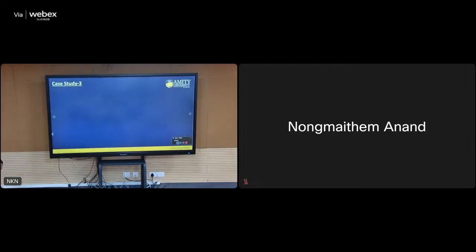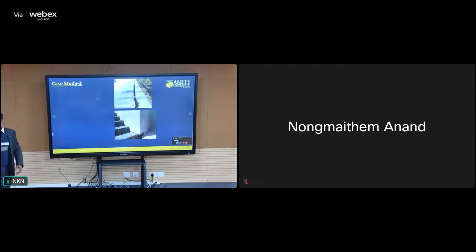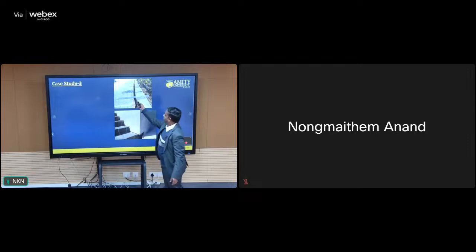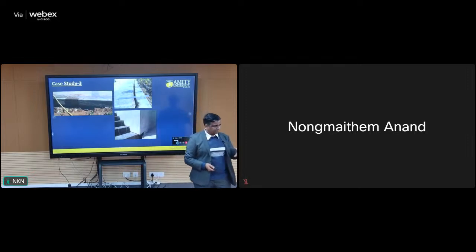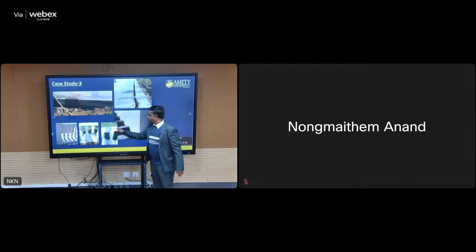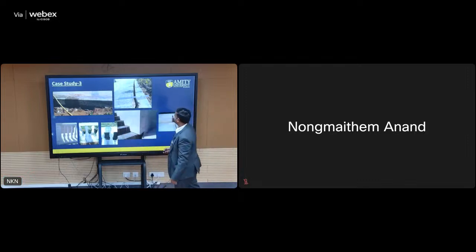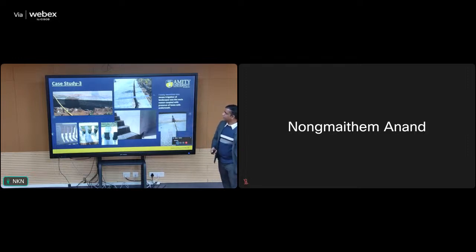You can see the staircase going down. Wherever there are plantations, gaps have been created in the pavements. You can see some of the soils that have subsided and are creating problems. You can see these balustrades are getting gaps. In some places, the flat slabs on the ground have subsided. A scale has been kept to identify how much it came down. You can see the gaps identified here.